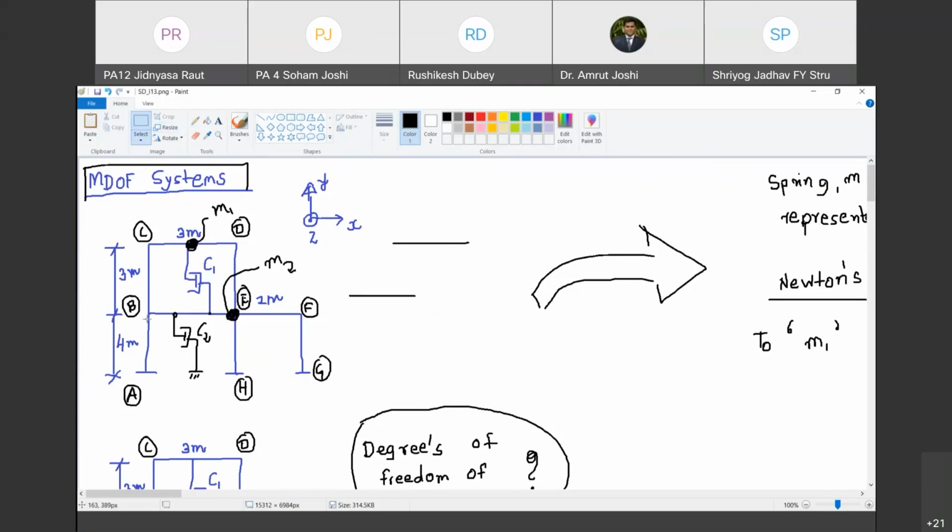Okay. Similarly, the soffit of the first floor slab is connected to the ground. So relative to the motion between ground and this top story, corresponding to the relative velocity between these two levels, there will be a force that will get induced in this damper element with damping coefficient C2. Happy? Yes, sir. Okay. Now let us go ahead.